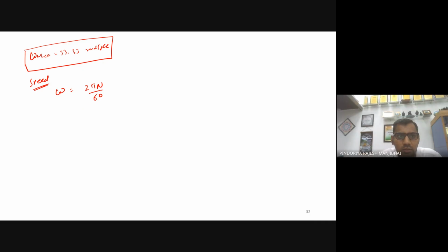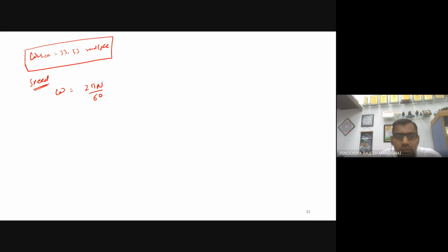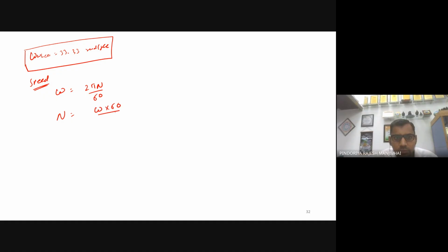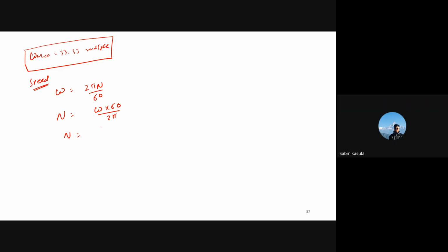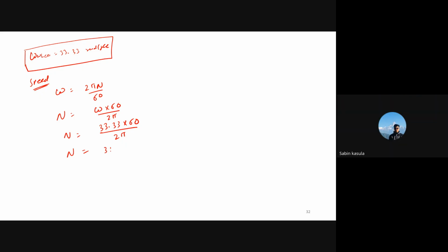Now what is the n? Speed in RPM. So we have to calculate the n, correct? Yes, sir. So n equal to omega into 60 upon 2 pi. And what is omega? 33.33 into 60 divided by 2 pi. Now you calculate. What is the value? 318.27. So about 319 RPM.